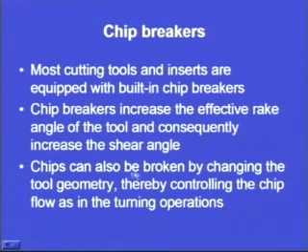The chips can also be broken by changing the tool geometry, thereby controlling the chip flow as in the turning operation. So, tool geometry can be modified so that the chip breaks when it slides over the rake face of the tool.